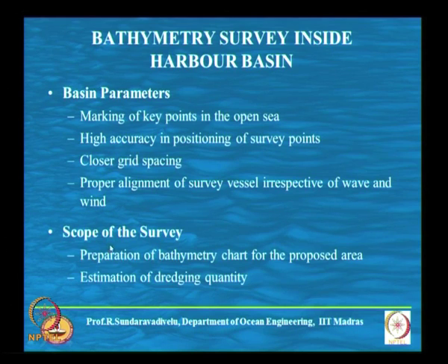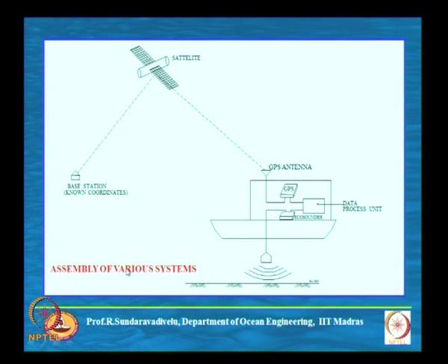What is the scope of the survey? This is the preparation of a bathymetric chart for the proposed area and estimation of dredging quantity. This is the maintenance dredging quantity. What we normally do is prepare the bathymetry, find out the water depth and see whether the water depth is as per the requirement. If not, you have to find out how much soil has to be dredged, and for that purpose this will be used. So this is the base station, this is the satellite, this is the vessel, there is a GPS antenna, and there is a sounding equipment.